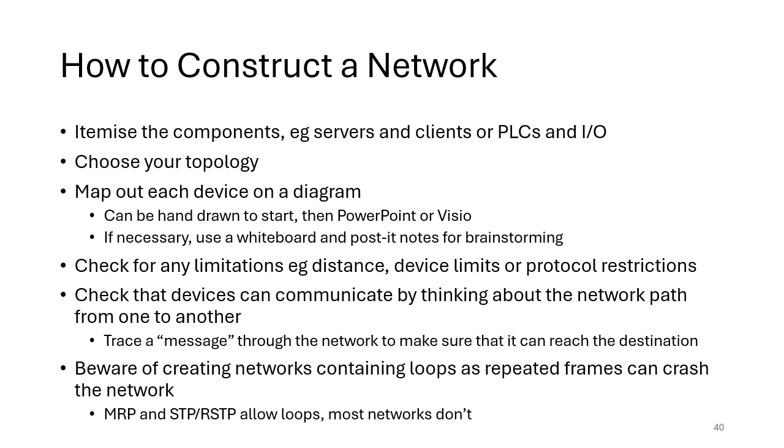So how do we construct a network? Often this is done for us. We would have an IT team or some sort of system development team. But if you're doing this yourself, you need to itemize all the components you're going to have. That would consist of servers, clients, PLCs, I/O devices, and also any other sort of ancillary device that's on there. May include routers and gateways, may include security technology.